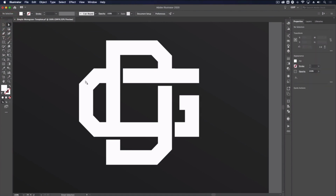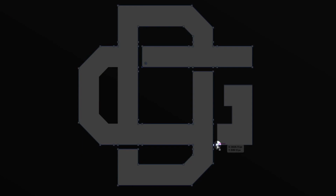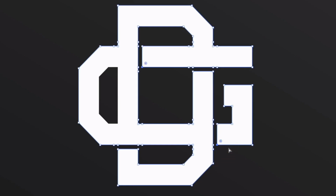Now you can accentuate this slightly by applying some angles to this. So with my direct selection tool, I'm just going to select the bottom anchor point on one of the cut areas, and I'll do the same on the bottom right section, and holding Shift and hitting right on my arrow key, I'm just going to create a slight angle, and I know they are consistent with one another. And then I'm going to do the same with the cuts on the underside of the G here.